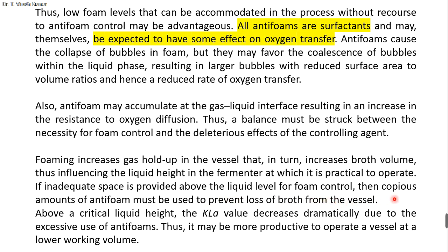That means, for example, if the total volume of the fermenter vessel is 1 liter, you should not use the media for the full 1 liter. You can operate only 700 ml. That means only 70% of the total volume you can use. If your vessel size is 1 liter, you can use 700 ml. The remaining 300 ml will be left for the foaming. You have to anticipate that the foam can form, and you have to control the foam.